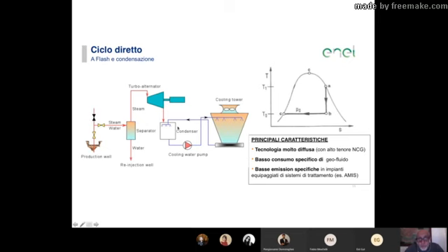But even if it is more efficient, the environmental problems are the same. Now in Italy, they now use what they call AMIS, which is abatement of hydrogen sulfide and mercury. And so the way they do it, they oxidize the H2S to SO2, and then they dissolve the SO2 into the geothermal fluid.